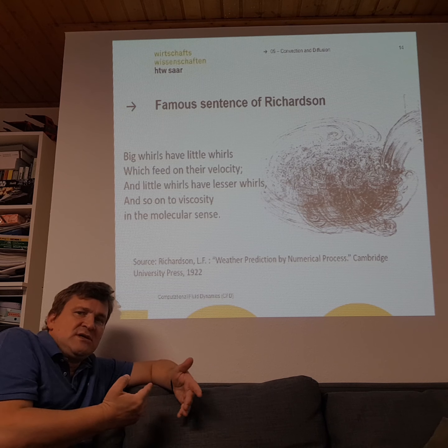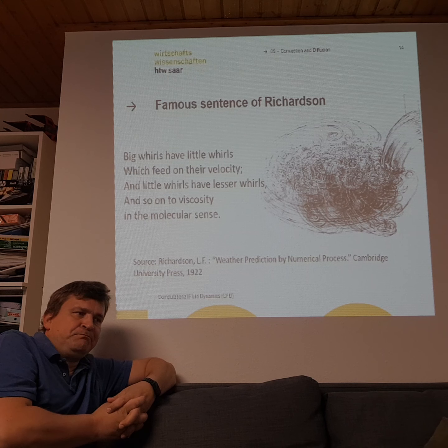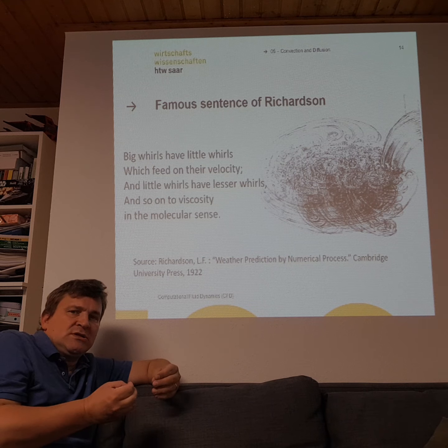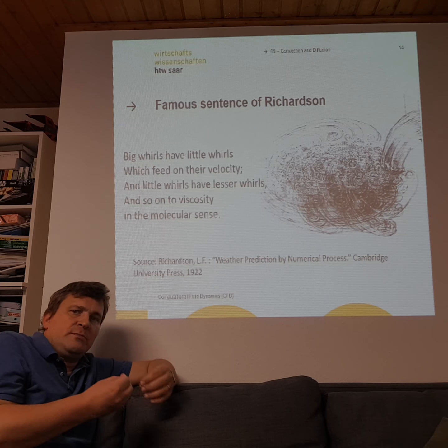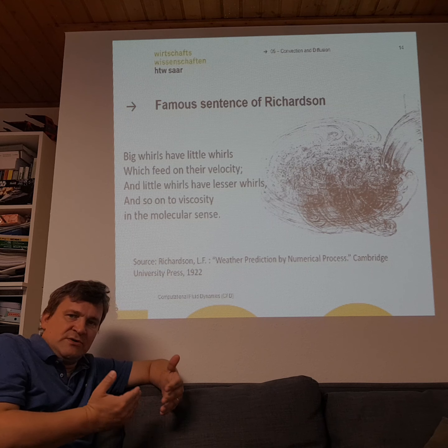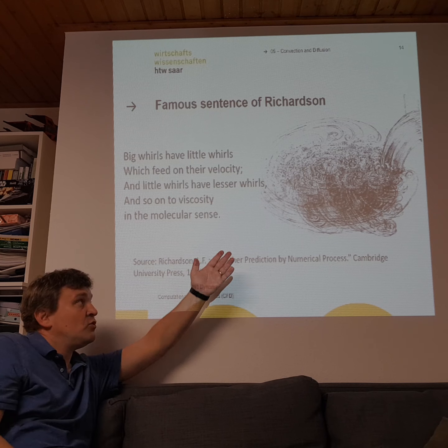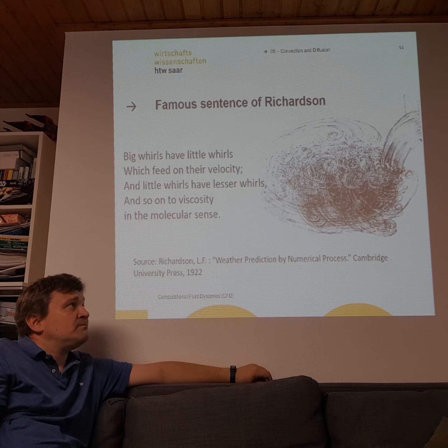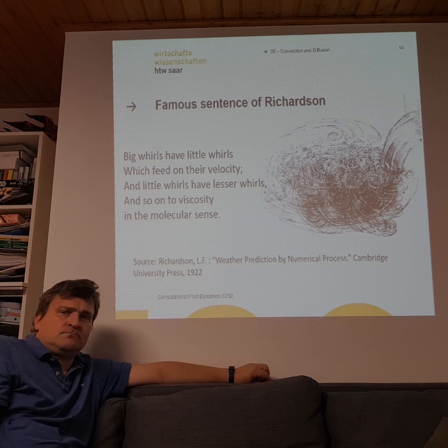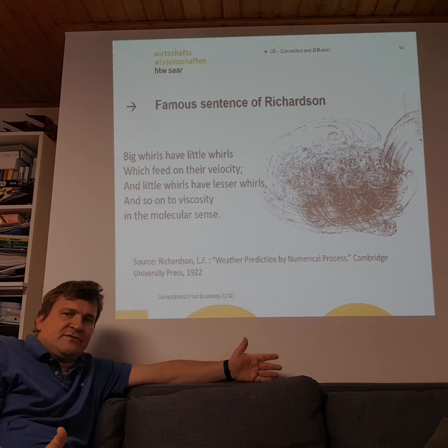And if we use easy models like SST models or K epsilon models, the swirls are modeled with a kind of turbulent viscosity. Of course, that's not a really detailed description of physics, but more or less this swirl, this chaotic behavior of the fluid can be described by an overall turbulent viscosity.